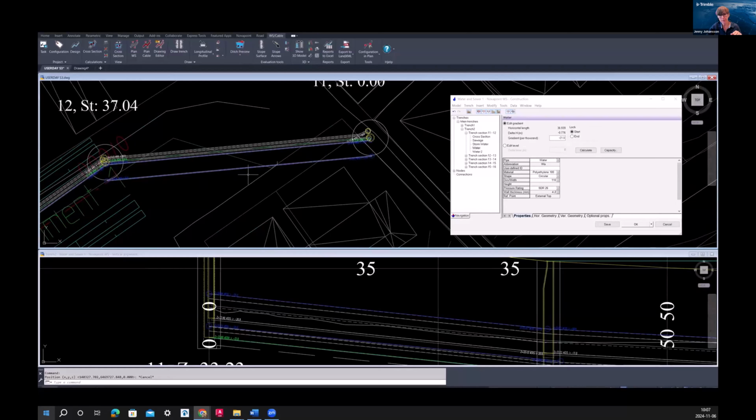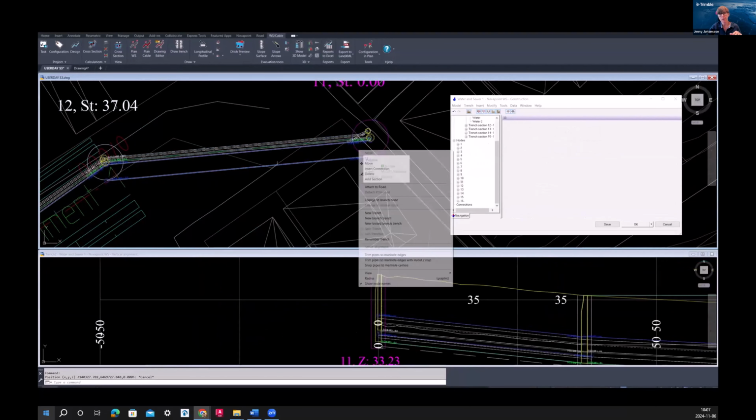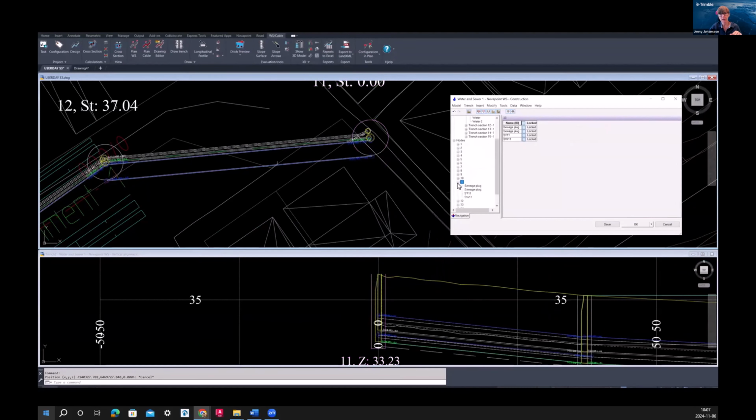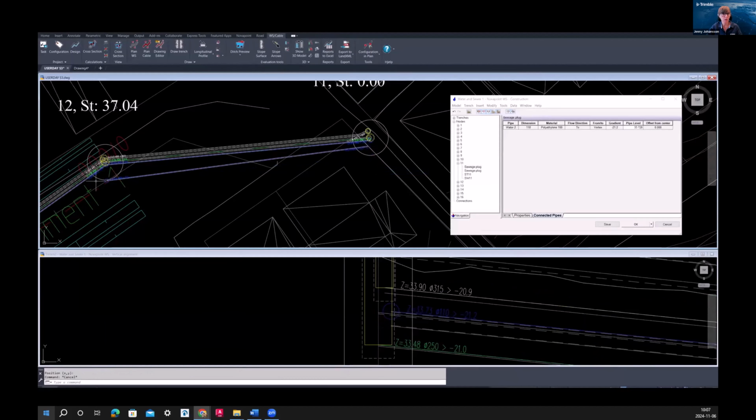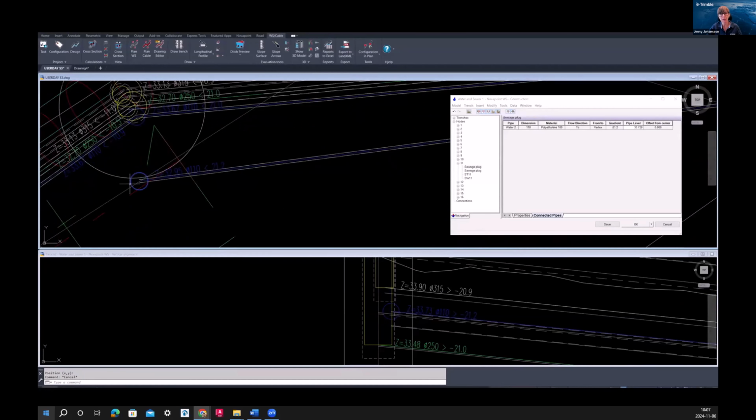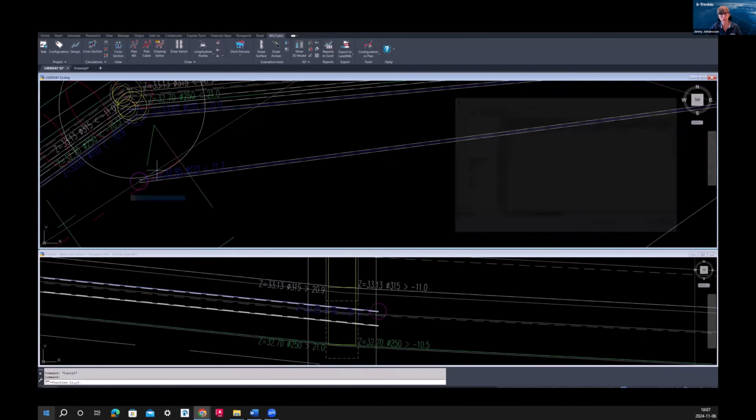And as we can see, we get a connection at each end of the pipe. If I right-click one of the nodes, I can see in the dialog that we have 4 connections connected to this node. So even if it looks like the pipe is far away, it's connected to the node. It's easy to move the connections just by right-clicking them and moving them to new positions.